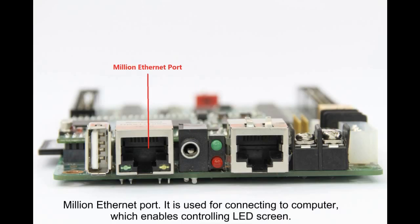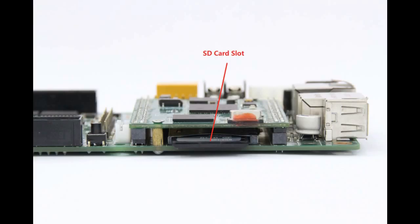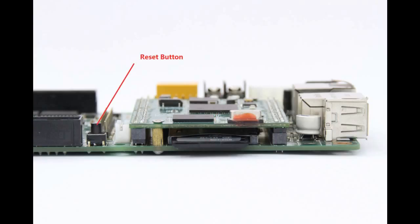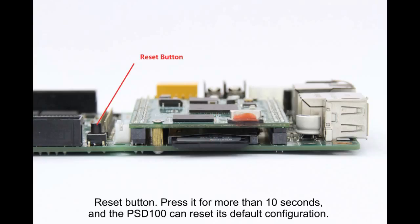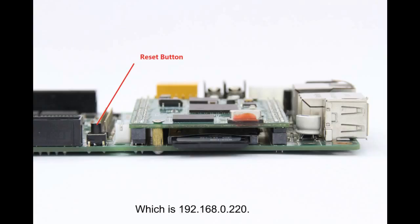The Mini Ethernet port is used for connecting to a computer, which enables controlling the LED screen. The USB port is used for supporting U-Disk plug and play. The SD card port is used for supporting SD card plug and play. Reset button: press it for more than 10 seconds, and the PSD100 can reset to its default configuration. Usually it's used to restore its default IP address, which is 192.168.0.220.